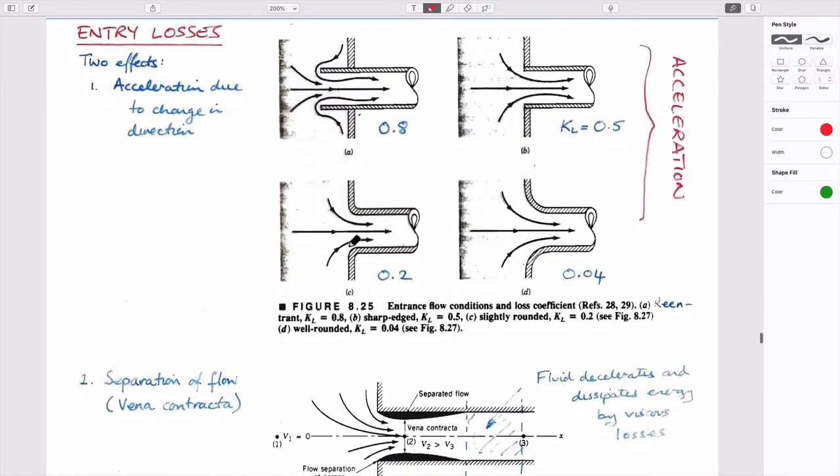But the physical characteristics of this are that it varies with the geometry of changing flow. We made the point last time that as you go from a stagnant tank that has no velocity to moving in a pipe, physically you're accelerating something. Zero velocity here, some velocity here. And so from F equals ma, if you're accelerating something, you have to apply a force to move this packet of fluid from here to this point here. And so that force that you're applying to accelerate it from zero velocity to some finite velocity is eaten up as energy delivered to the system.